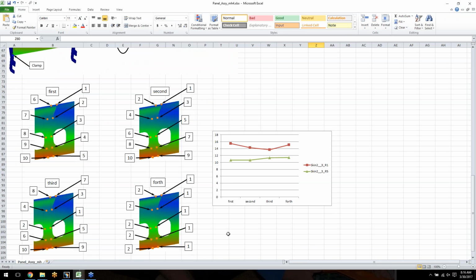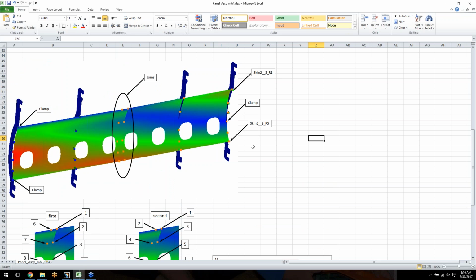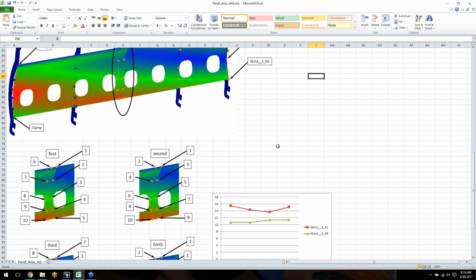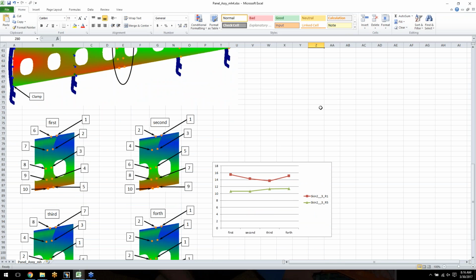Plotted on a simple chart, it shows you this is the bottom measure at this corner, the top measure at this corner. There is obviously larger deformation at the top than at the bottom, mainly because the clamping point is not exactly halfway up, so this will vary more. But the third option seems to put the two variations closer to each other.